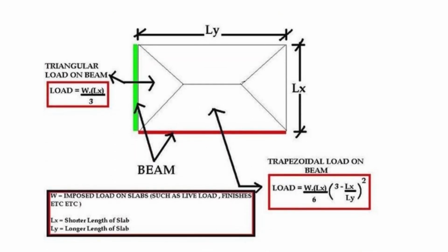If a slab is supported on two sides only or supported on all four sides, but the longer side to shorter side ratio is greater than 2, it is termed as one-way slab, see figure. The beam's distributed load is computed by multiplying the segment area, trapezoidal or triangular area, by the slab's unit load divided by the beam length.